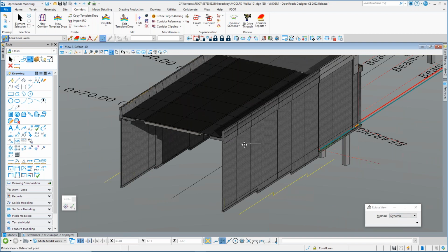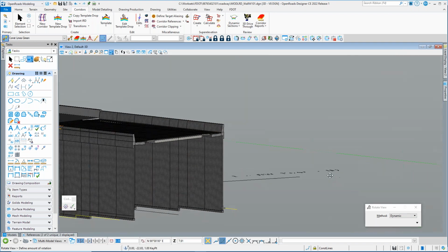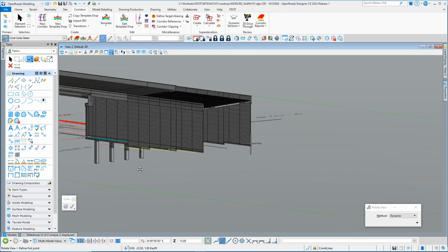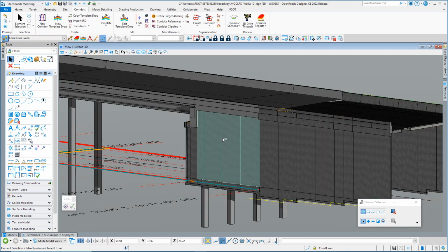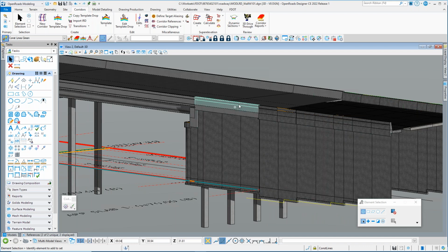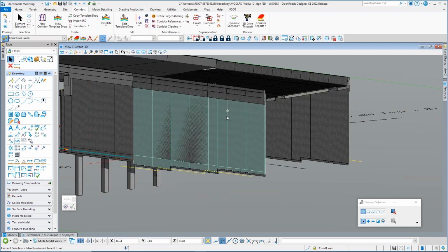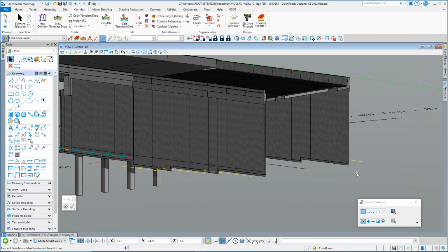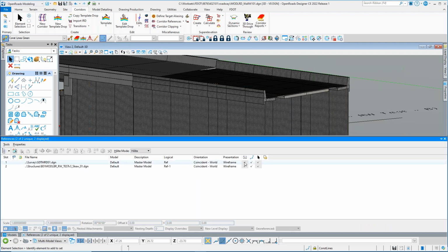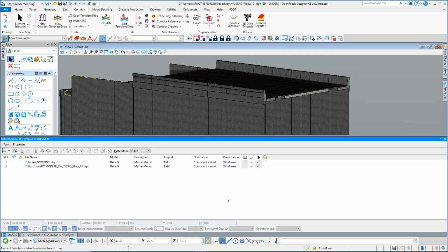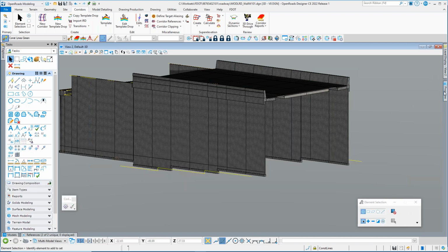So we're going to rotate the view here, and let's just choose another target. We'll spin this around and see what it looks like. That seems to look pretty good. We've got our wall and our footer, our leveling pad under our approach slab. Got the front face of that, and we've got our roadway MSE wall, and that seems to look pretty good. I'm going to come back in and turn off these references real quick so you can see what the result of the MSE quantity component turned out to be.